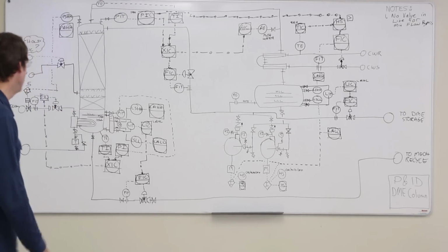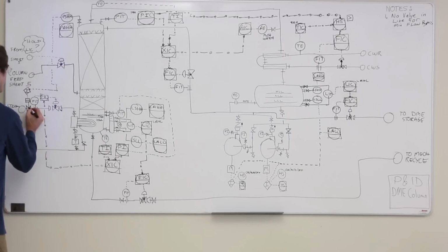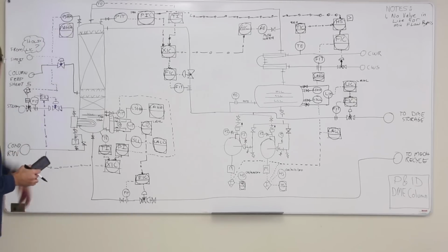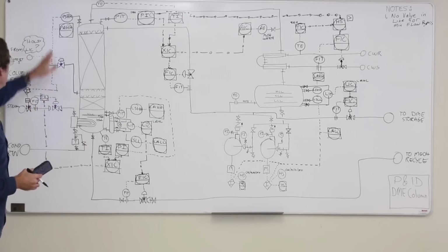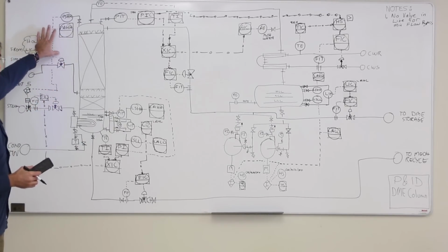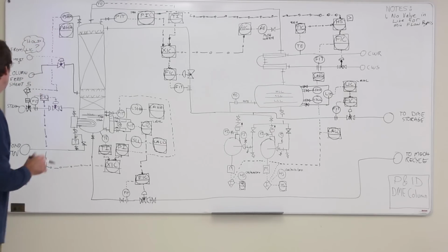I'm going to assume the steam control valve is knackered. And I'm just going to shut an isolation valve on the inlet to the steam system based on that high pressure switch. So now this is all hardwired through here. The control system could be not working, and this system would still all work properly.